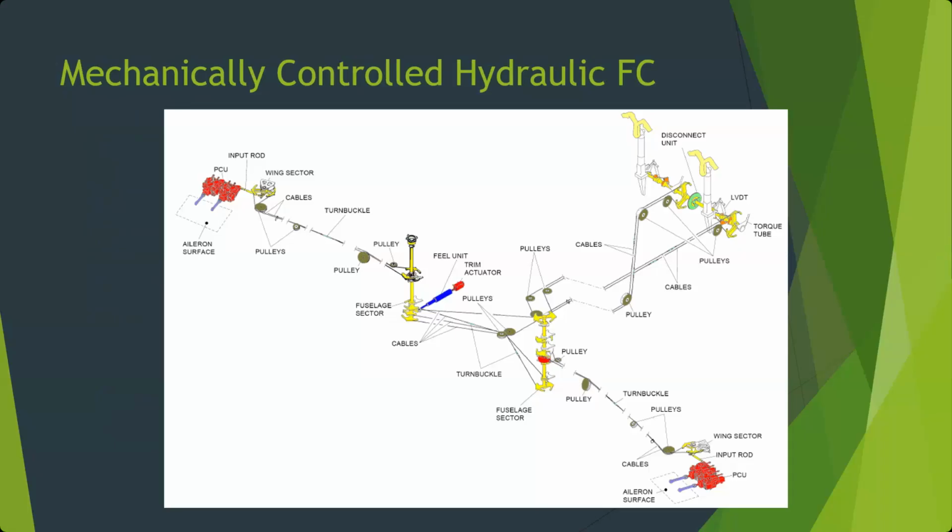Redundancy. They're going to operate on different hydraulic systems. So in this aircraft, for instance, it's a 3. This is an Embraer, either a 170, 175, 190, or 195. 3 hydraulic systems. So the left one is powered by hydraulic system 1 and 3. The right one, I believe, is powered by 2 and 3. But I could be mistaken exactly.